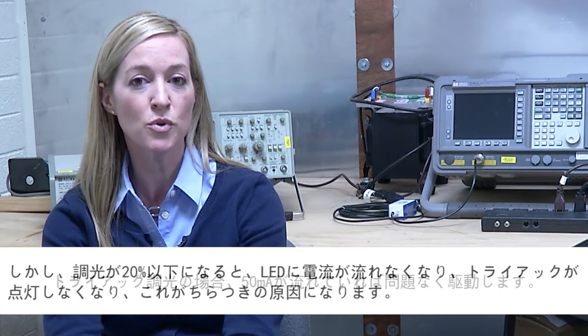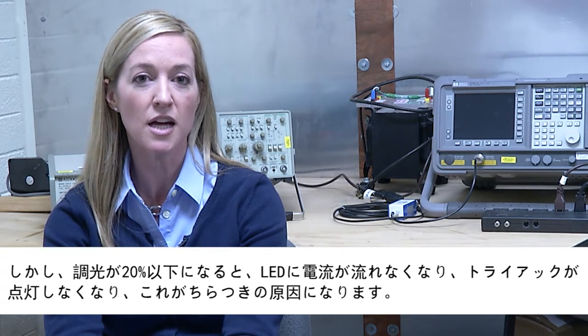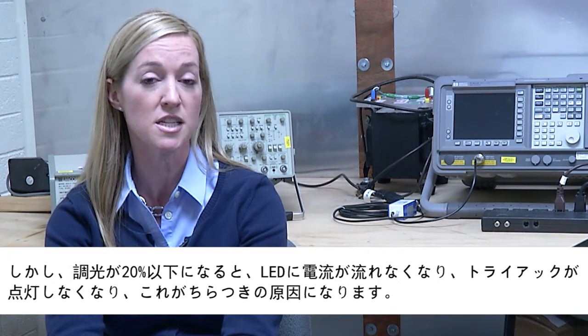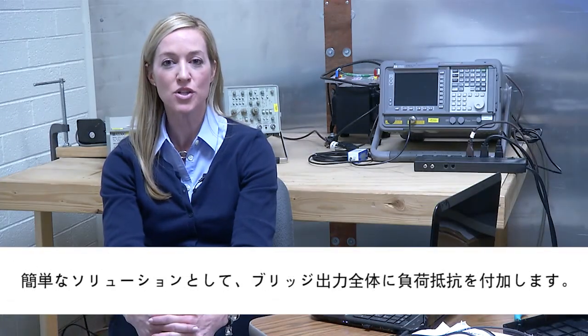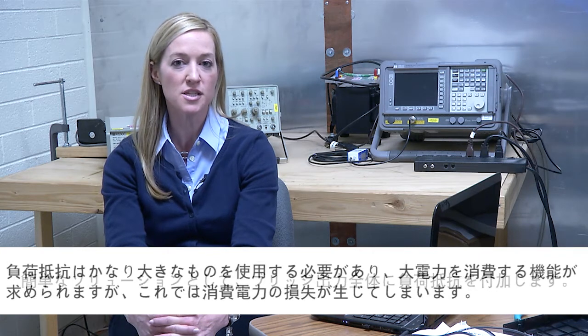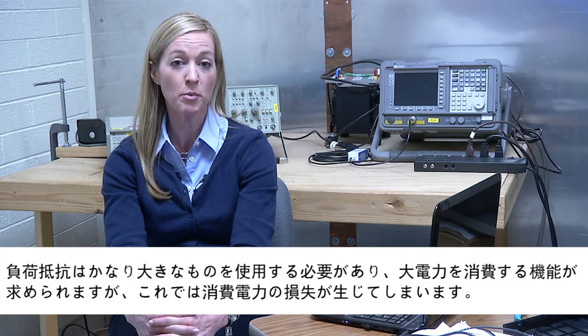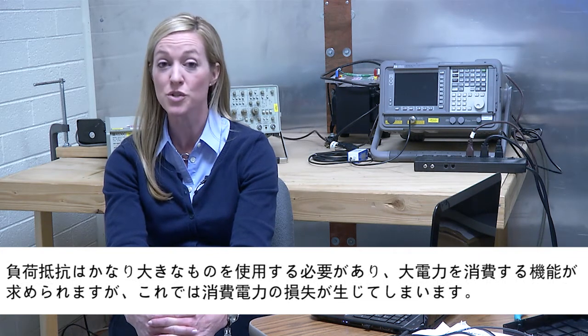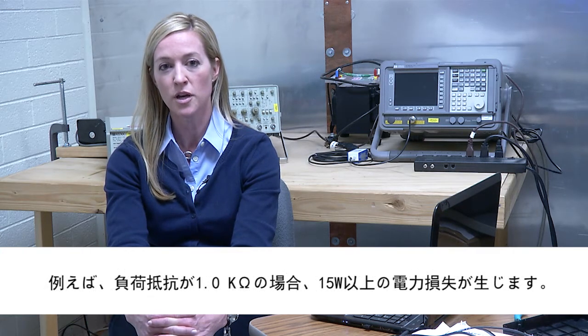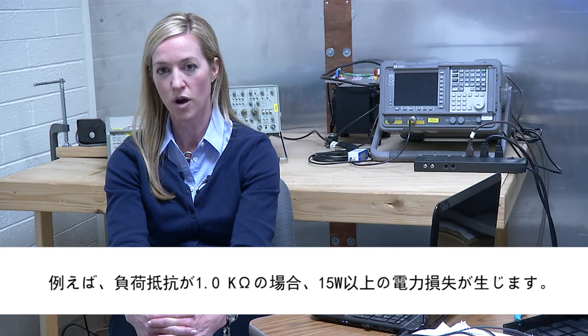The 50 milliamps is sufficient for the Triac and the dimmer to turn on and operate correctly. But when the dimmer is moved below 20% on, the LEDs will stop drawing current and the Triac will misfire and cause the LEDs to flicker. A simple solution is to add a load resistor across the output of the bridge. This resistor would need to be very large and capable of dissipating a lot of power, which is wasted power. For example, if your load resistor is 1 kiloohm, you will be dissipating greater than 15 watts.